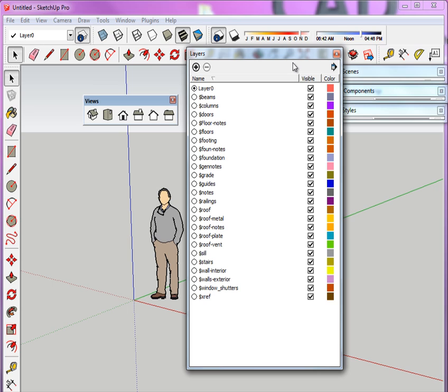All right, so once you go through your list, you should have prepared a list like what you see here, okay? I use the $ sign so I can separate the layers that I created in SketchUp versus the layers that I'm importing from the AutoCAD file, okay? I use separate layers so I can control the two different things separately. So, for example, what we're going to do first is we're going to keep layer 0 always current, all right? But for this one time, we're going to switch over to the XREF layer, and this is the layer that we're going to place our DWG on.